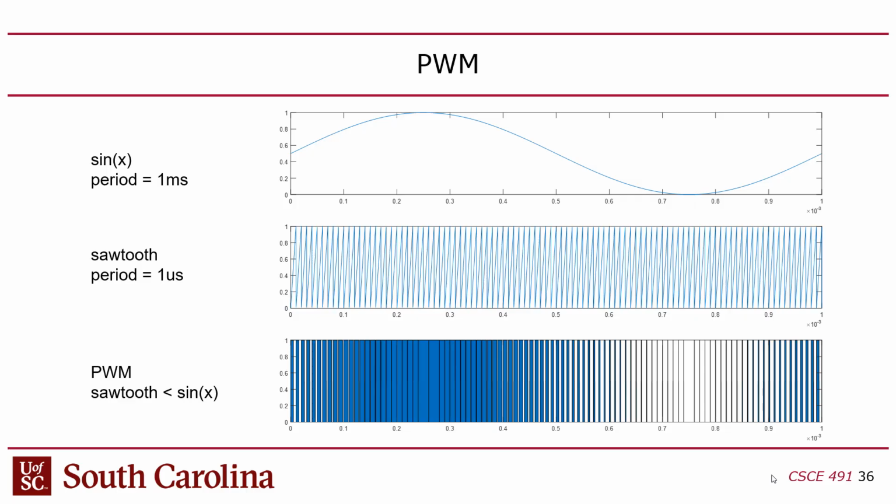So you just compare the signal to be modulated against the sawtooth, and the result of the comparison between the two becomes the PWM signal. So you can see here that the PWM, when you look at it visually, of course this is compressed quite a bit, is real dense wherever you have a higher value signal you're modulating, and it's sparser here, right? Does it make sense?